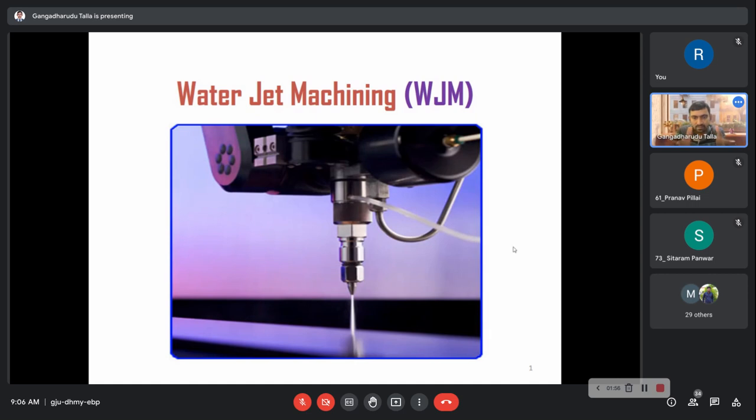So a mixture of abrasives and gas comes like a jet and hits the workpiece, and brittle fracture of the workpiece takes place if the workpiece is brittle in nature. In that way we are removing the material. Mostly abrasive jet machining is very much suitable for machining of brittle materials only. However, it can be used for ductile materials with less effectiveness or efficiency.